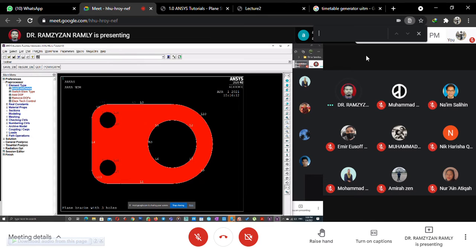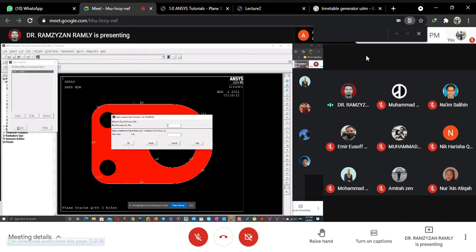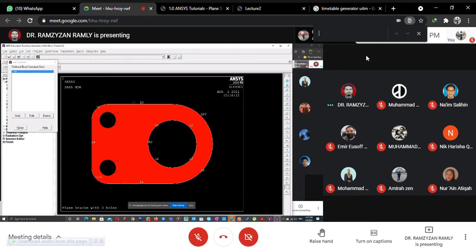And after that, we have to define the real constant. Add, delete, none defined. We have to add. Okay, this is plane 182. What thickness does it have? 20 mm. Okay, close.